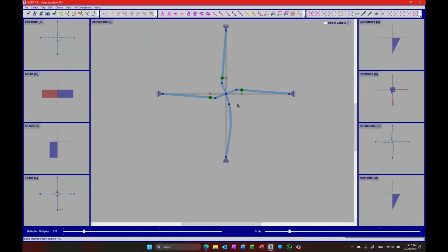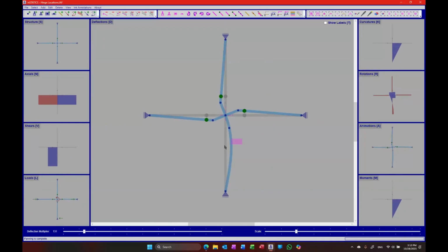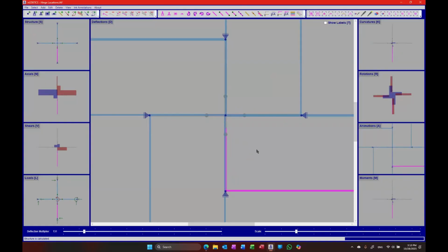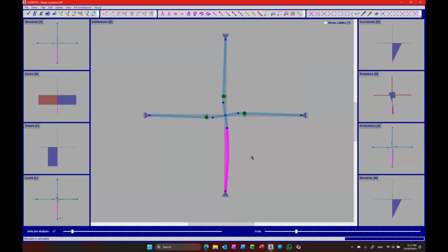By looking at this, now what I want you to see is that if I add a pin here, this is again not stable. It just has excessive deformations. So instead of flashing, it's just showing excessive deformations, which is another way of showing us that it's singular. In floating point operations in computers, sometimes the determinant does not come out exactly zero, so it's still kind of invertible, but not really in the engineering sense.